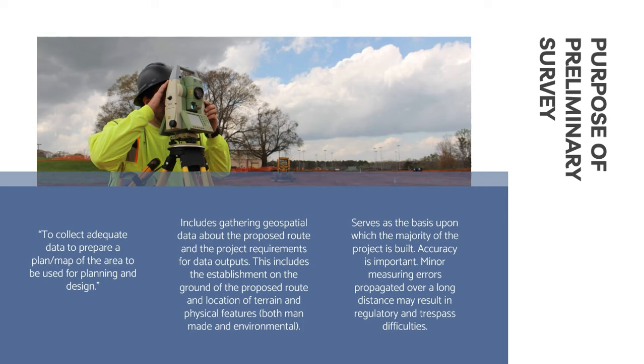The preliminary survey serves as the basis upon which the majority of the project is built. Accuracy is important. Minor measuring errors propagated over a long distance may result in regulatory and trespass difficulties. It is more than simply a survey. It is knowing the suitable horizontal and vertical datum, standard data libraries, and laying the groundwork for future project work.